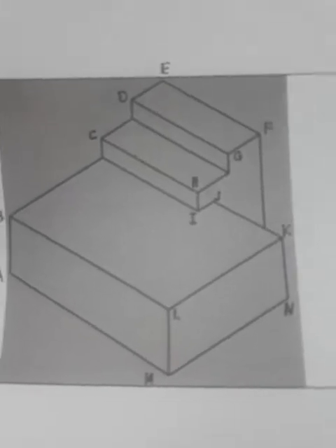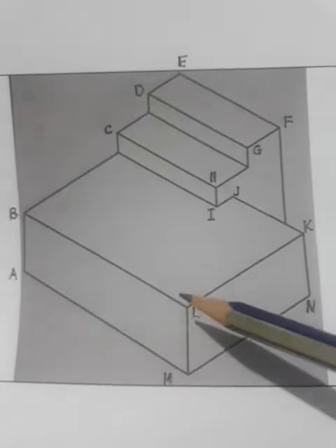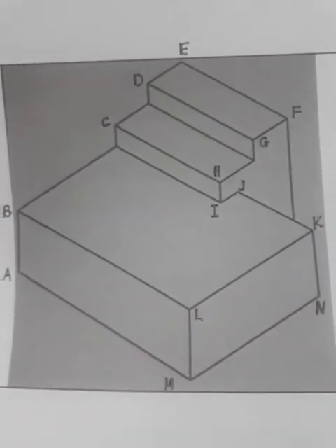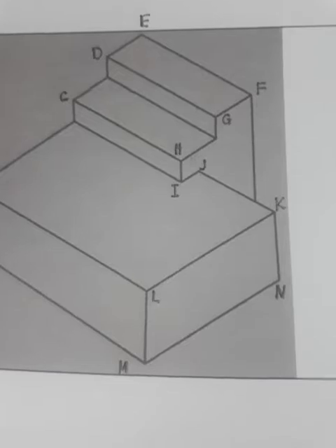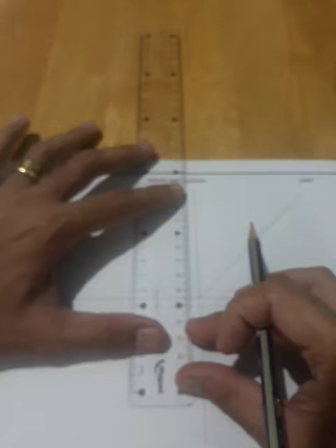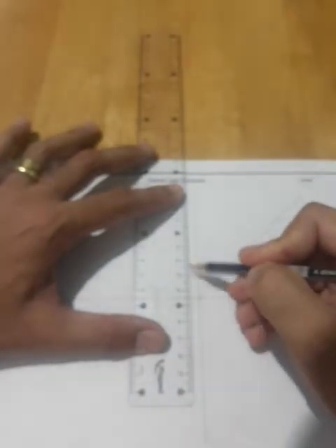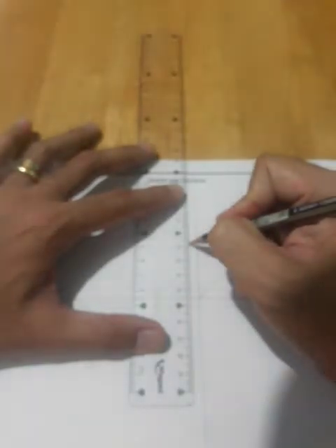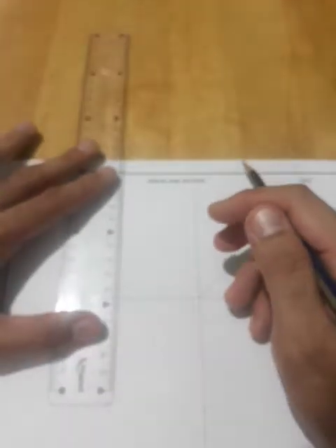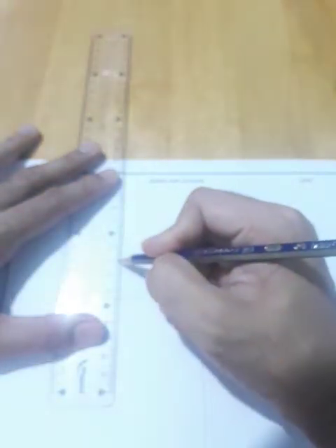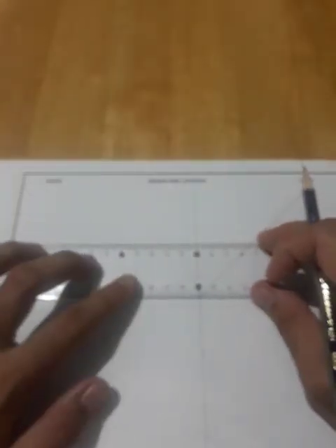Of course, on the top view, it is specified that we need to show points L up to point K. So, based on our dimensions a while ago, it is set at 32 millimeters. So, let's lay out 32 millimeters. So, 32 millimeters will be somewhere here on this portion. So, let me measure 32. So, 10, 20, 30, and then 2. Okay, that's 32 millimeters. To make it balance, measure on the other side. 32 millimeters. 10, 20, 30, 32 millimeters. So, let's connect the two points.